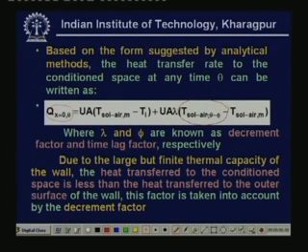time lag. That means let us say that I am calculating the heat transfer rate at 6 p.m. on a particular wall. I want to know what is the heat transfer rate from the wall to the conditioned space at 6 p.m., and let the wall have a time lag of 5 hours. Then T sol-air at theta minus phi is the solar temperature of the wall at 6 minus 5, that is 1 p.m. So that is the meaning of theta minus phi.